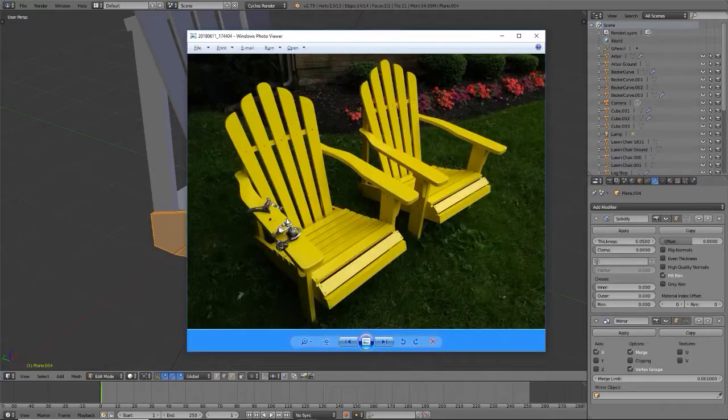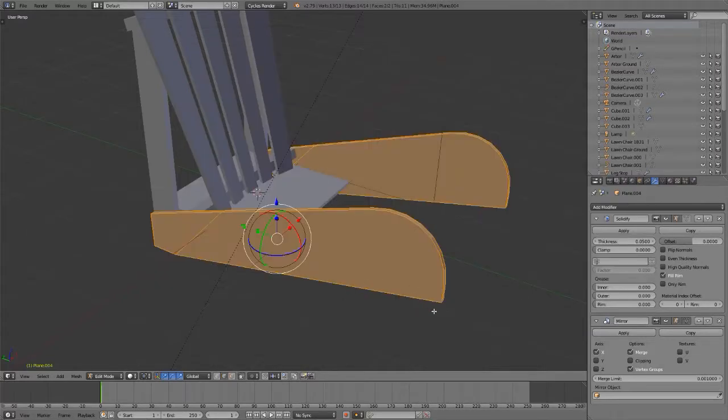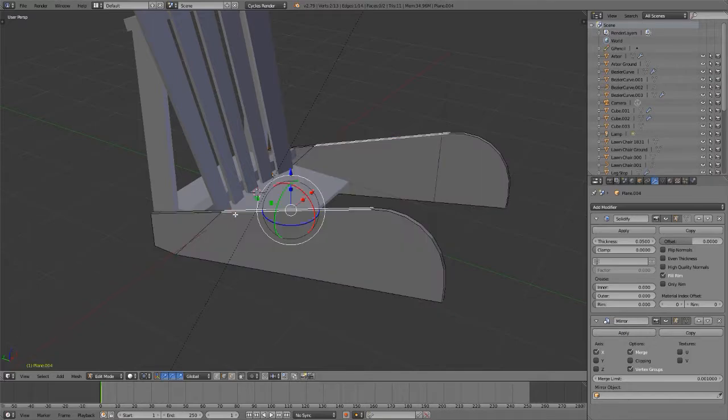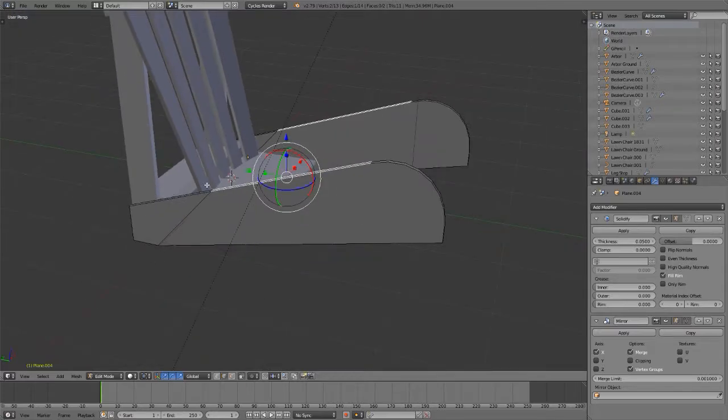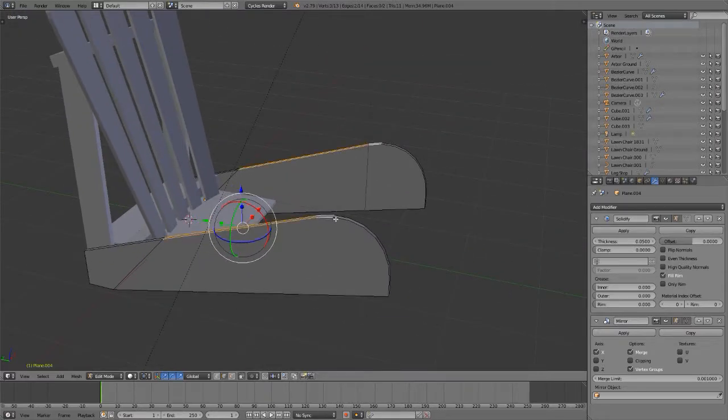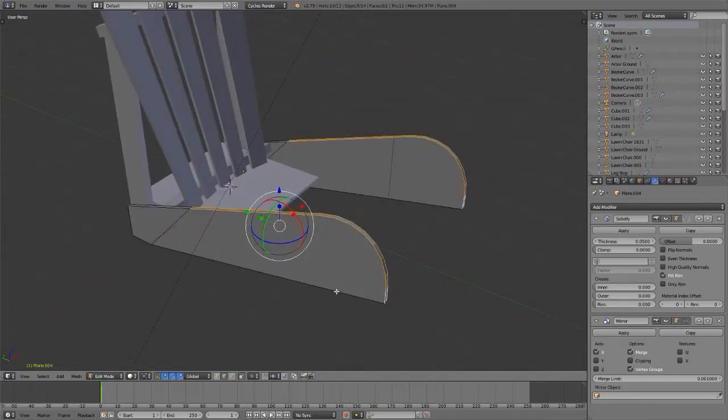How far down do those slats go? They go all the way down to the bottom of that turn near the sharp edge. Remember I said we got to move this vertex ahead of the slats of the back? This is why. Select that edge. Shift right-click select all the edges that have seat slats stuck on them. Shift D, make a copy. Enter. P, separate by selection.